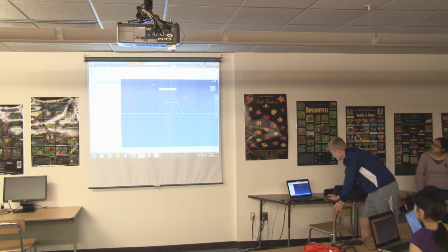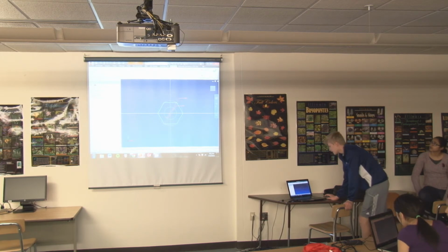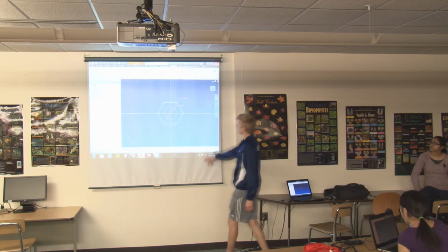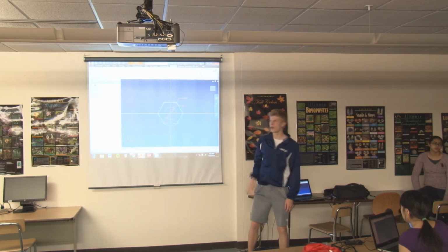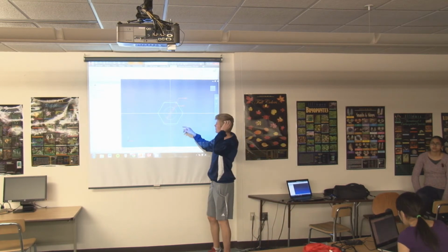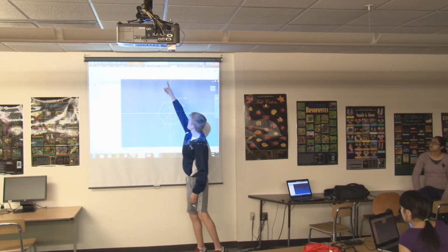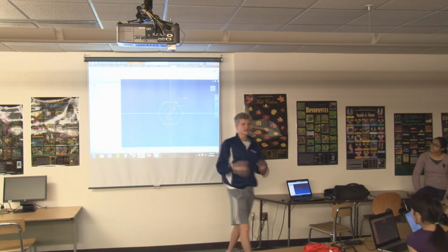So now those dimensions still aren't in a perfect hexagon. So what I'm going to do is clear out of my line tool, and then go up to here. These are your geometric constraints. Now here's where there are a number of ways of doing this. For example, this constraint up here creates a horizontal line constraint. When you click on a line with that, it will be forced to be horizontal relative to your axis here. Up there is a parallel line constraint. So you can make these two lines parallel, those two lines parallel, and those two lines parallel, and that'll force it into the hexagon shape.